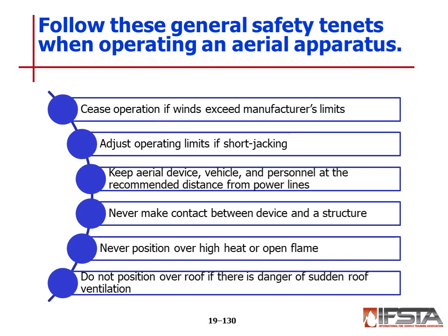Cease operation if winds exceed manufacturer's limits. Adjust operating limits if short jacking. Keep aerial device, vehicle, and personnel at the recommended distance from power lines. Never make contact between the device and a structure.